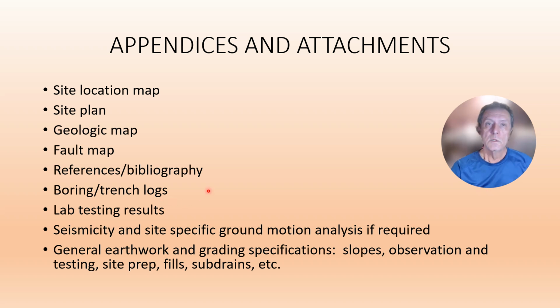You want to include your lab tests and explain what they mean, seismicity if required, and then general earthwork and grading specifications. These are usually standard sections included within just about every engineering geology report that are up to the standard of care as to recommendations for slopes, site prep, etc.